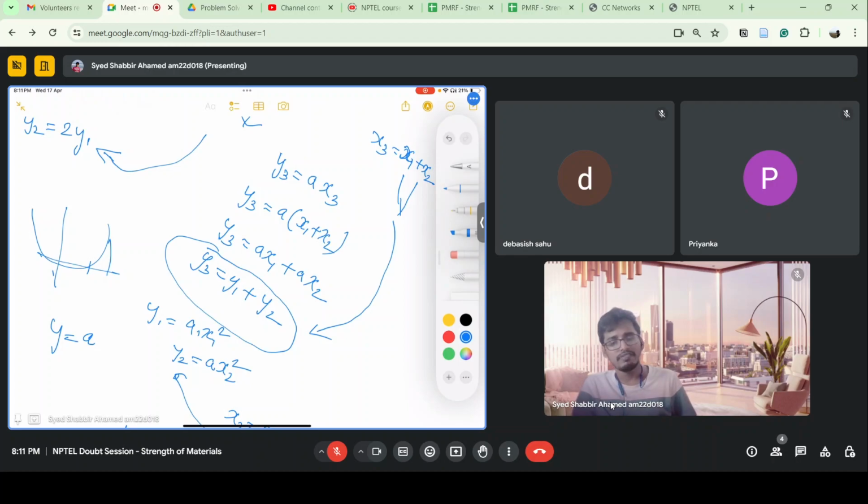So when we do a tensile test for a steel rod, it doesn't fail with a crack perpendicular to the direction of application of load. It fails with a cup and cone fracture, right? That basically means that it is failing in shear. So ductile materials fail in shear. Remember that. That's why we get the cup and cone failure. So theories of failure we have seen.